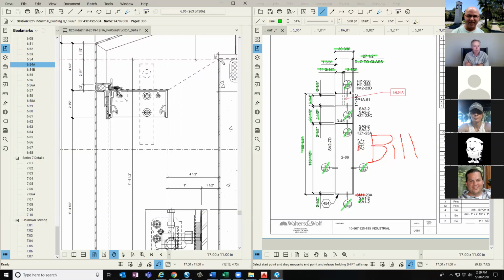There was a time when Dave Morales was working with us that he said to keep those in there, so I've been going for that. If they're shown in the drawings, keep them in there, because structurally they're helping the head. I thought that was odd, but he said that because the head channel is a channel, popping that in there helps hold it together structurally. So he always said keep them in there even if they're not visible. I don't know if that's something we've changed since then.